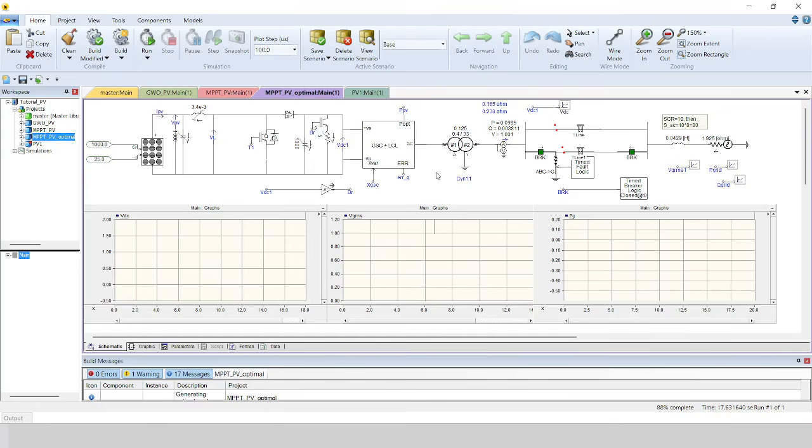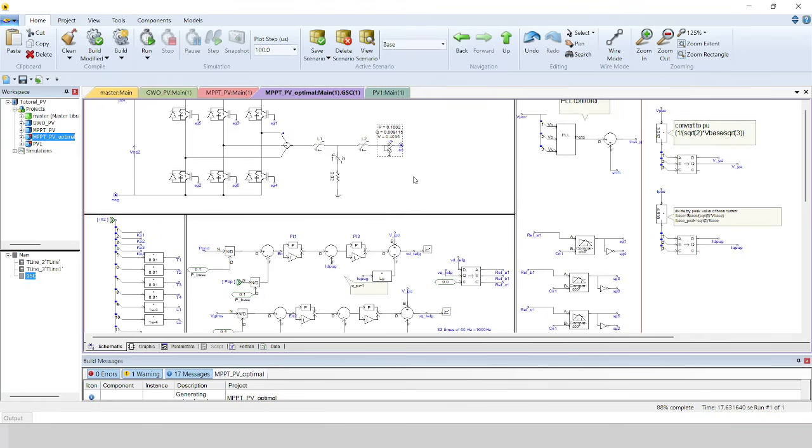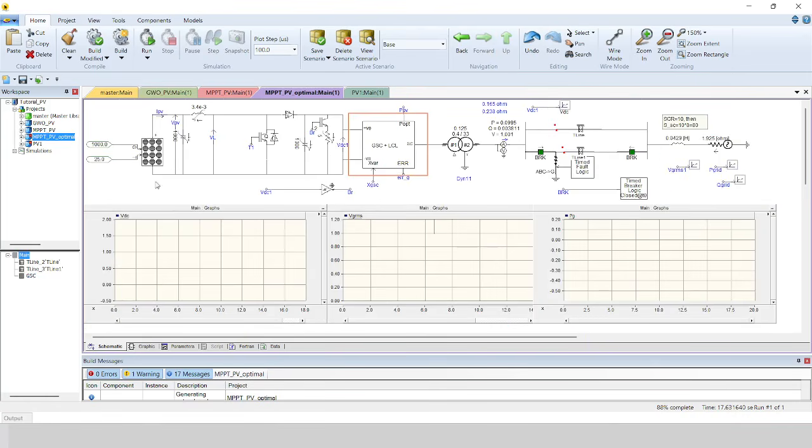Now, the same as I did in the wind turbine, I'm going to design this controller by using optimization, and also design the same LCL filter and the shift angle of the PLL for best operation. But now it is connected to a PV array, not the wind turbine. And this is the DC to DC converter. And also the same, I am using a braking resistor to protect the system from the over voltage.